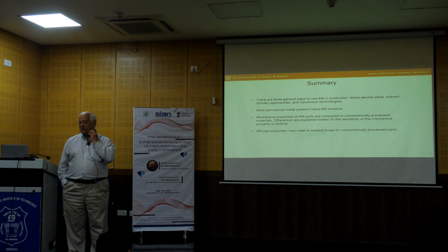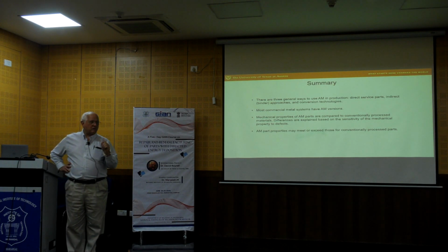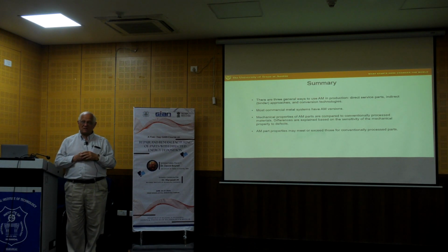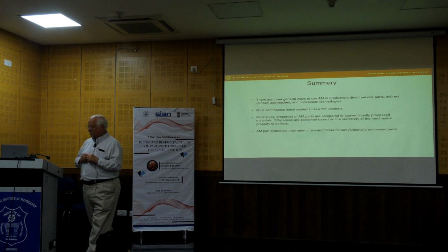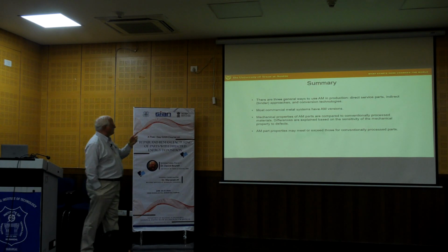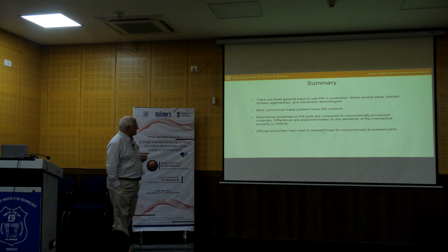So when we went back and looked at the metal systems that are available for additive, what we would find is that for the most part, they all have excellent weldability and excellent castability. That doesn't really guarantee, but it almost guarantees that we can also process the material using fusion-based additive, whether it's powder bed or directed energy deposition. Okay, so anyway, that's number 2. So we have AM versions. The mechanical properties, I think, can be compared to conventionally processed materials.